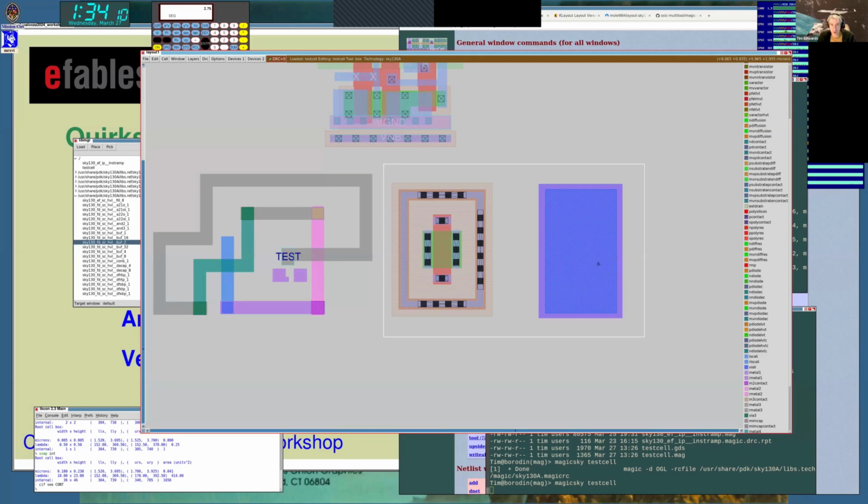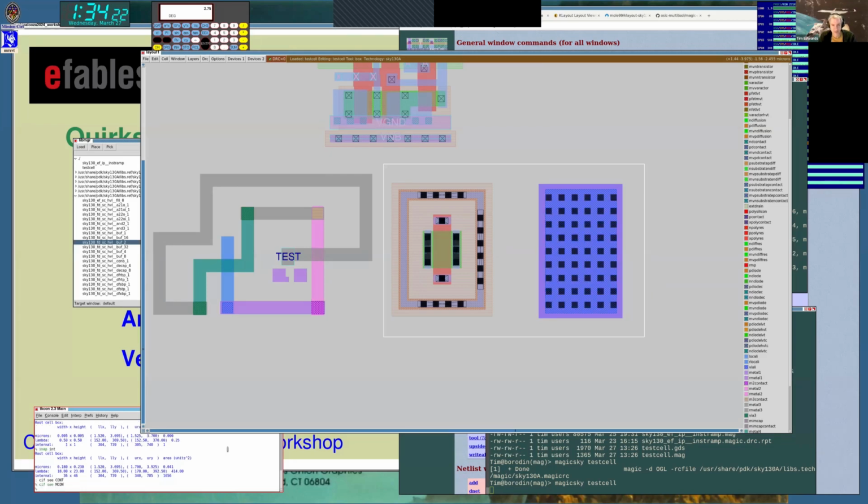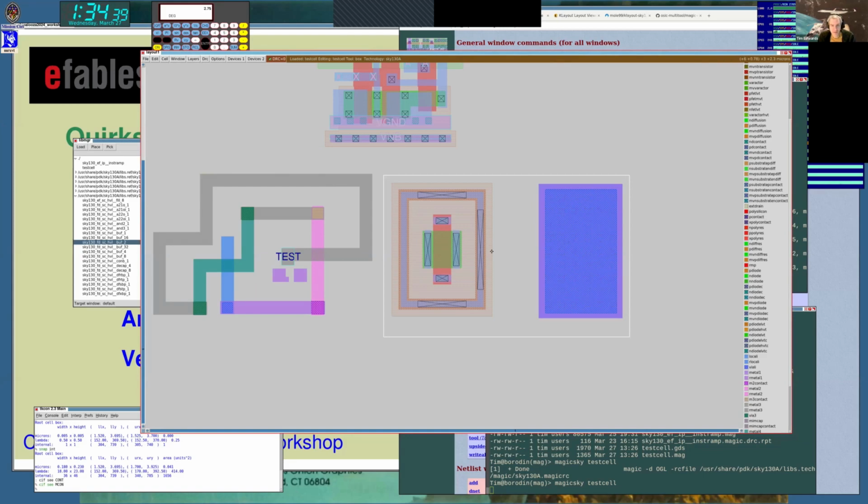And for local interconnect to metal 1, MCON is the term for it in Sky130. So that shows me where all the contact cuts in this array are. That's how Magic deals with contact cuts. And if I don't want to see these contact cuts anymore, I can go to the layers menu, clear feedback will make them disappear, or the command feedback clear. Oops, spell it right.